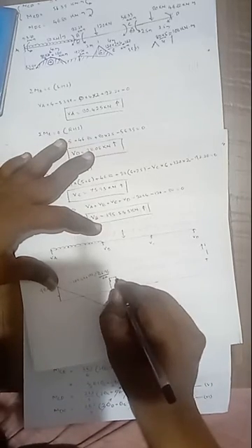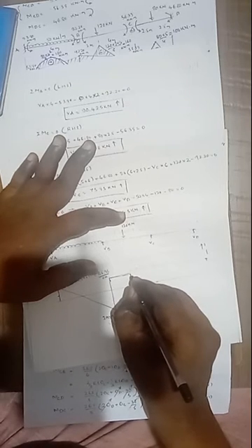Then here from B up to the point load, here there is a UDL, the variation is a straight line, it decreases gradually like this. Here from this point to this point, this one is constant. Here this one is 85.96, this one is minus 120. Then this becomes 85.96 minus 120, that is minus 34.04.